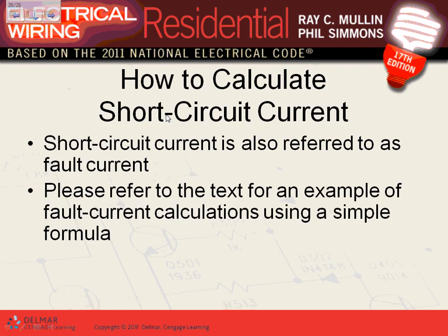And I promise you, this is just touching the short circuit. We'll get into that one, guys, in detail. Okay, any questions, guys, about the short circuit? Take the full load of the transformer, divided by the impedance, piece of cake.